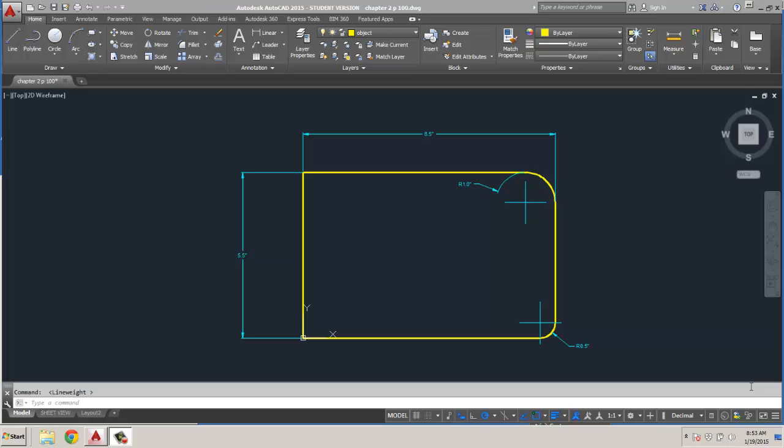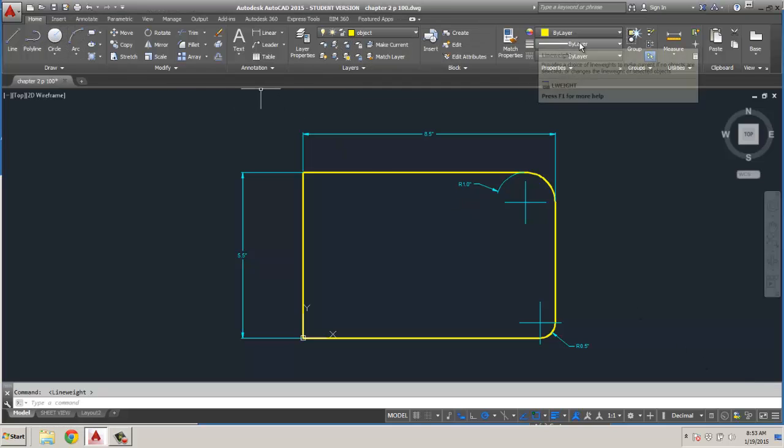All right, I just wanted to clarify a little bit on the offset. I found some shortcut methods to put these two holes in here. The first one comes off the bottom, but I'm going to place these both off the top. So I'm going to go to my circle command. I'm already in my object level layer, and I'm just going to type in the letters TK, enter.